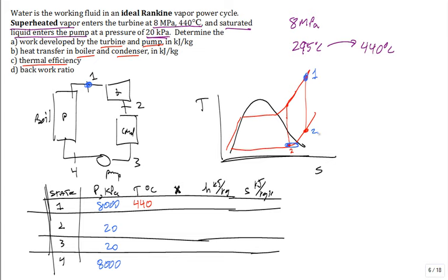vapor as well. So what about if I know the pressure and the temperature, 2 independent intensive properties, I can go and get the enthalpy and the entropy at state 1. But what fixes state 2? It's isentropic flow through that turbine, true? So pressure and entropy are what I use to fix the state 2.